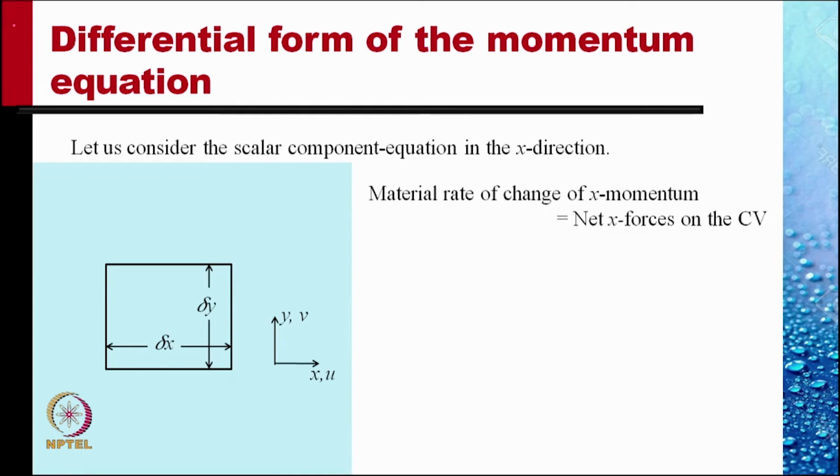Now the momentum theorem states that the material rate of change of x momentum contained within the control volume is equal to the net x force applied on the control volume. The Reynolds transport theorem is used to obtain the material rate of change of momentum in terms of the rate of accumulation of momentum plus the net efflux of momentum.